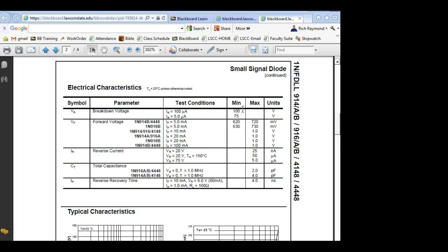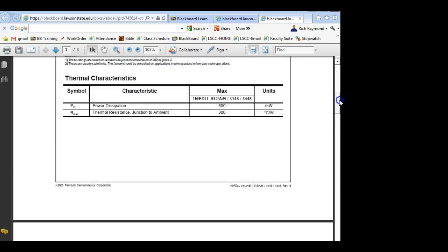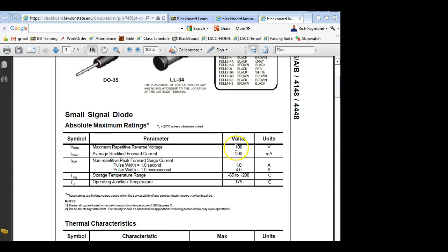It's 100 volts. Some books call that PIV, which stands for peak inverse voltage, which means inverse means what? So this is what we're really looking at, right? This guy right here. And that's not RMS. Y'all understand that? That's peak. So you need to know how to calculate peak when you put this thing into something, because if I put this thing across 120 volts AC, then peak is going to be like 170 volts, right? You understand that?